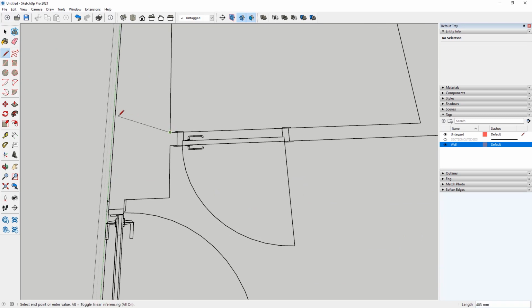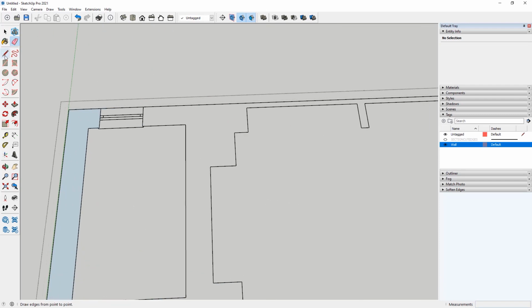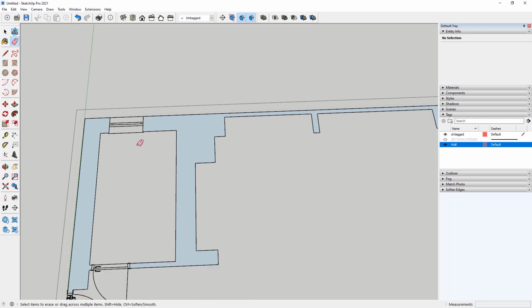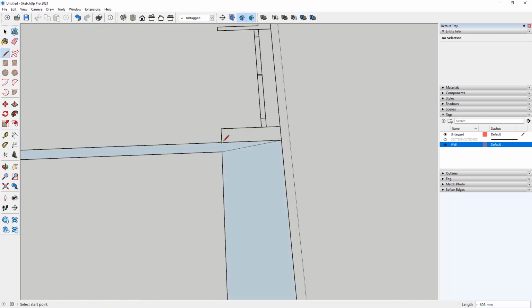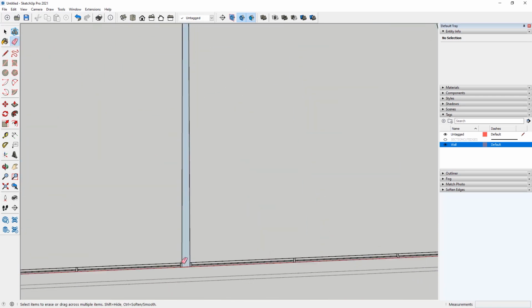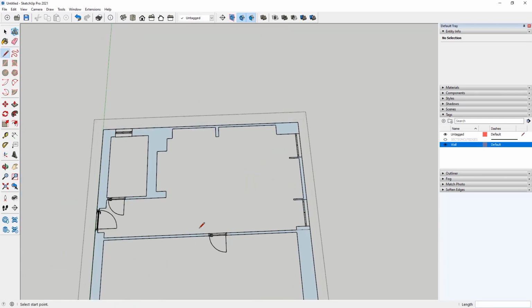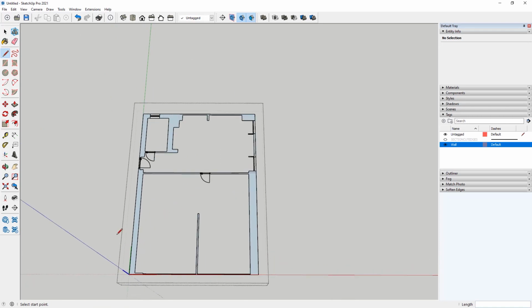We need to draw in each closed contour an additional line to get the surface inside, and I need to repeat these steps for all the contours to finally get all the necessary surfaces. This is something you will probably need to repeat every time you start your work in SketchUp. The more contours you have, of course, the more time you will need to spend to close all of them to get the surface.